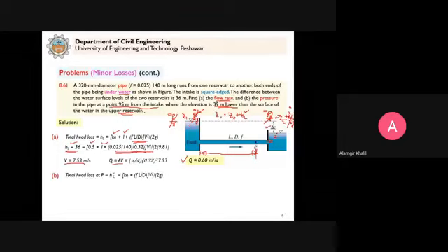So how do we proceed? Now, because the total head loss at P will be different, because this HL of 36 meter is for the entire system. Now we consider only up to this point P here. So we just look at the system up to point P. Because it is different than HL, let us denote this by HL dash.